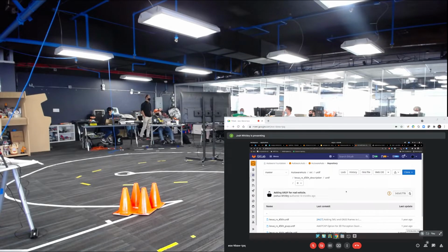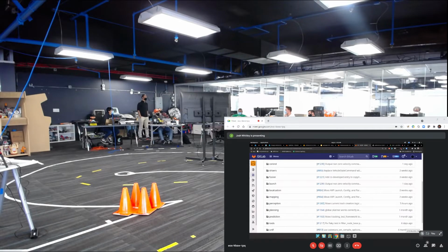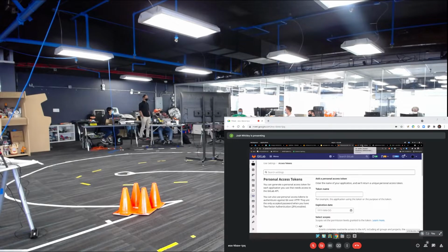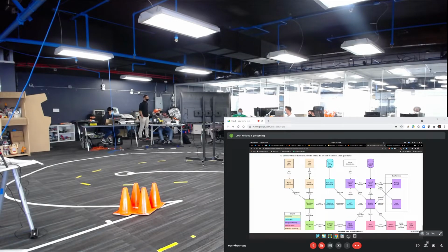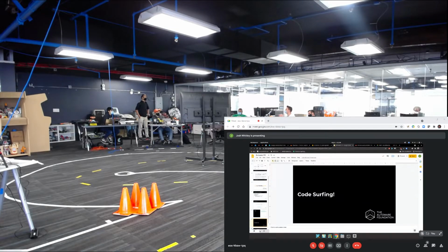Here's the thing with Autoware.Auto, we have ROS2. So whenever somebody comes up with hardware that enables ROS2, we can put it on the car. That's the new stuff we have here, the cool part. Whenever it has a ROS2 driver, we can enable it. For example, what you see here on the Jetson NX, we have the Jetson AGX Xavier, you can run it there. We have the Jetson TX2, we can run it there. So it's all from the same family, and it enables a lot of hardware we can put on.